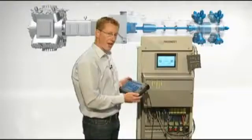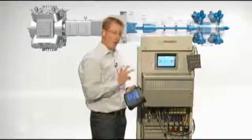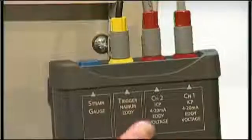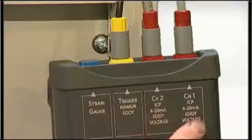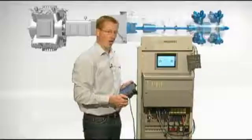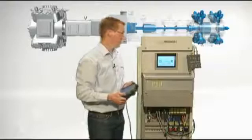And now we will start simulating with the Prognost SenSim 3 parallel sensors here, which is the trigger or the speed reference, and 2 parallel ICP channels, which will allow us also to mimic and simulate a voting scheme where we can have 2 out of X voting and safety limit violations.